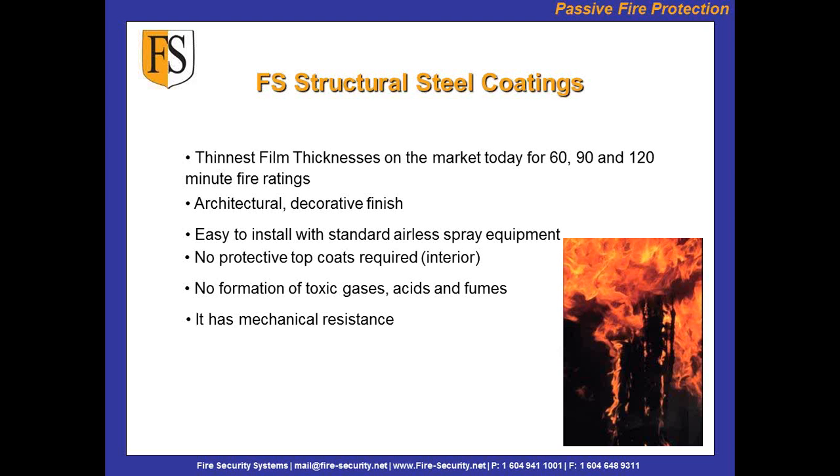So if it's going to be seen, you want an extremely nice surface, and you can really only achieve that with spraying, and that can be a Graco 33, 44, 56 to 1 airless spray machine. Usually with these types of materials, you only need up to about 3,300 psi in your machine, and you can get those from Graco. They're just plug-in and spray. They're not compressor driven. They're electric driven.